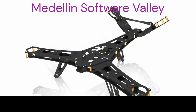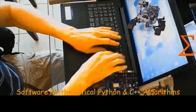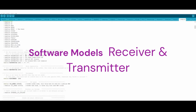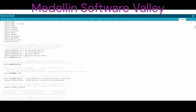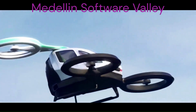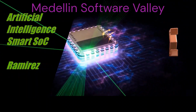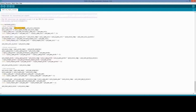The frame will have a mounting plate at the center holding all the digital electronic circuitries, 4 arms, 4 motor brackets to connect each motor to the end of each arm. The motors are brushless, identical to traditional DC motors but they do not have any brushes. Make sure to check the RPM, revolutions per minute, the motors can generate through the kV rating, that is the RPM constant of a motor.